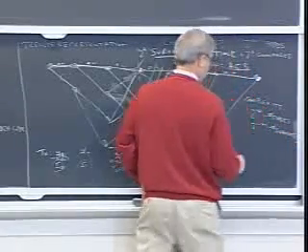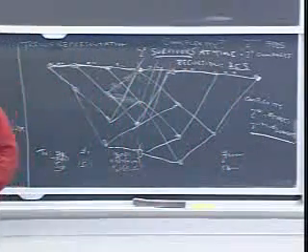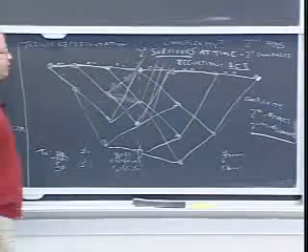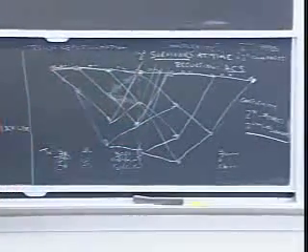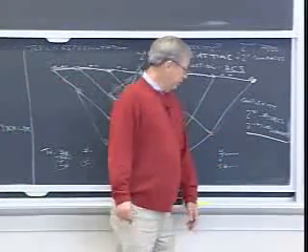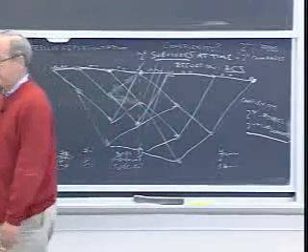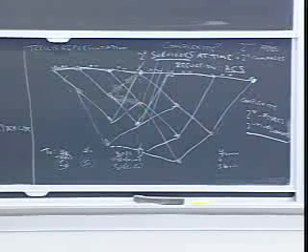I will argue a little bit later that the branch complexity is really more fundamental. You've got to do at least one thing for each branch. But these are practically the same thing, and so we say that the complexity of the Viterbi algorithm is basically like the number of states. If we have a 4-state encoder, the complexity is like 4.